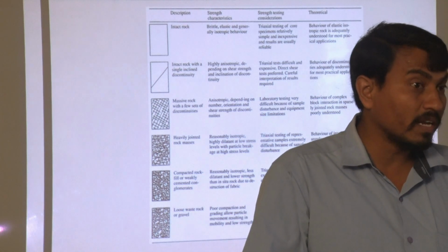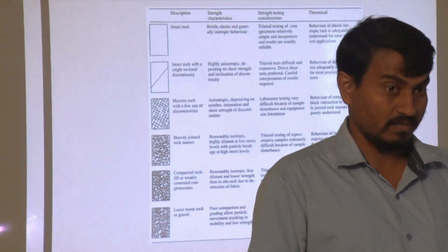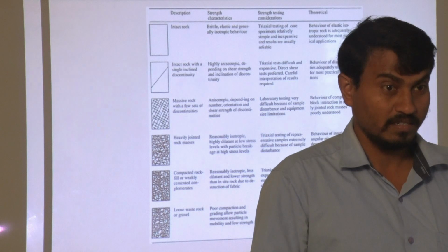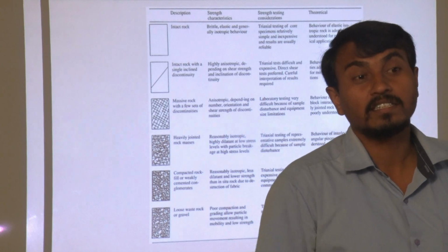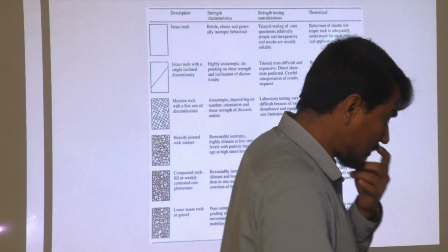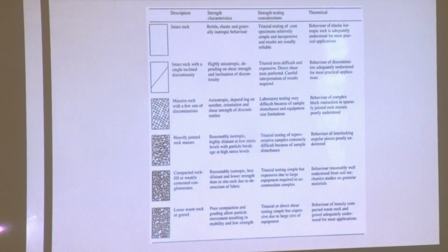A very porous rock layer is very tricky for engineers to design, particularly in a metro project in a city where residential complexes are present. So for this kind of rock, a rock classification system might not work. A rigorous amount of testing and modeling needs to be taken care of.